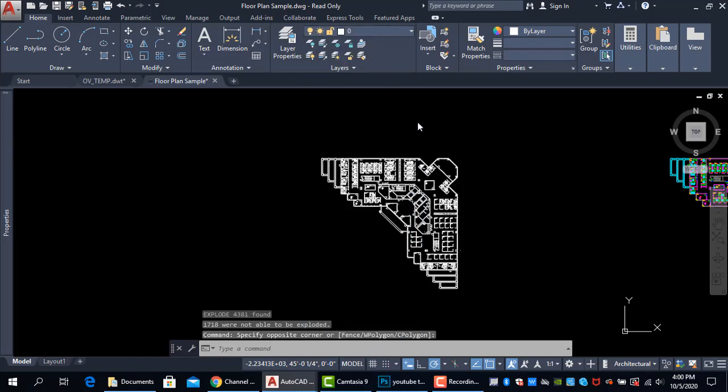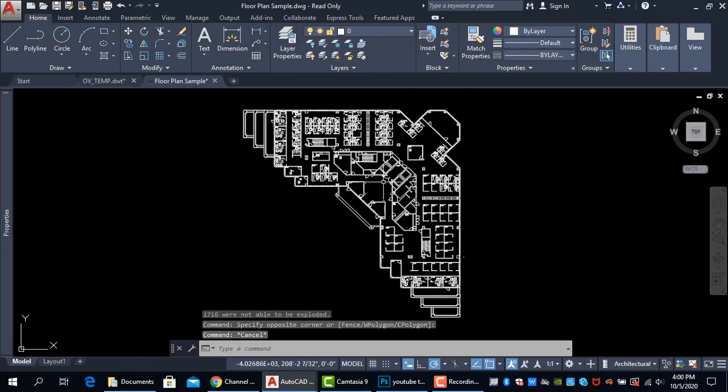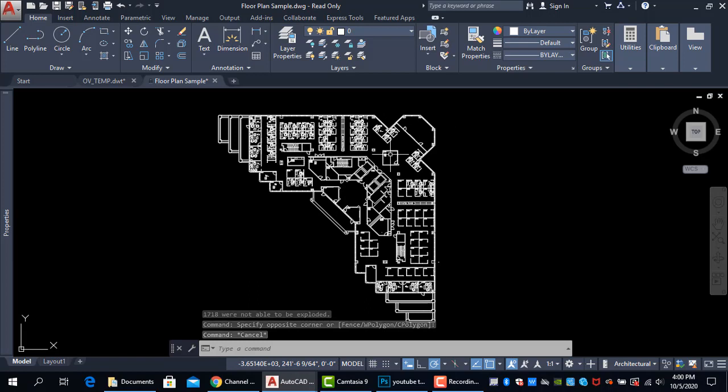Up to now, everything we have been drawing is on layer 0, because layer 0 is a layer that AutoCAD gave us in the ACAD template. That layer 0 is always there, and it's white. It's a layer that we start with. You should always leave layer 0 there. We're going to add layers in a bit, but layer 0 stays there.